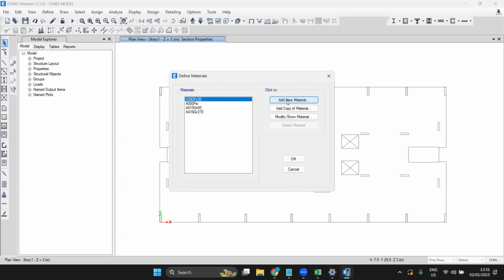Whatever it is, don't change the origin. Keep the origin as it is. Any number of ETABS files you can import with the corresponding tools, wherever you want to keep them. Even in one story, you can import multiple ETABS files. For example, I can import the slab edge first, then import the column second, then the beam if there is one, then the opening. That is also possible. Multiple ETABS files in one floor are possible. Correct?